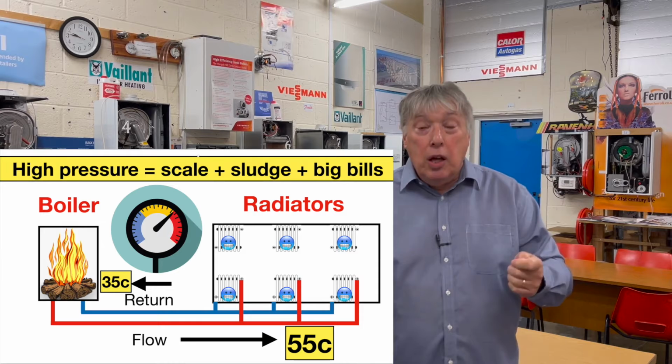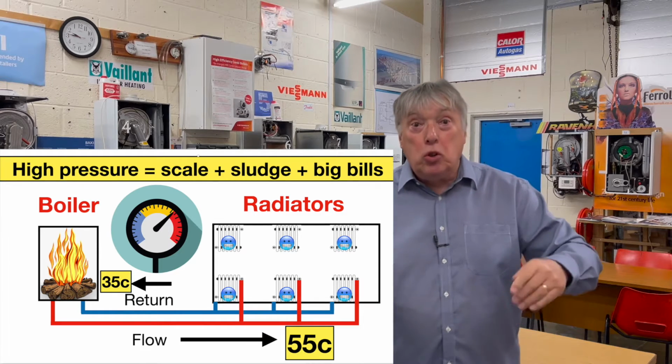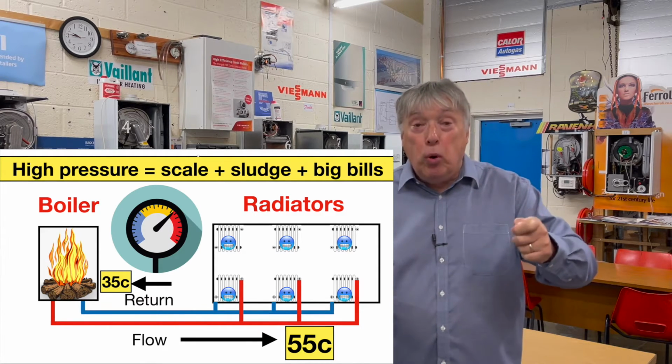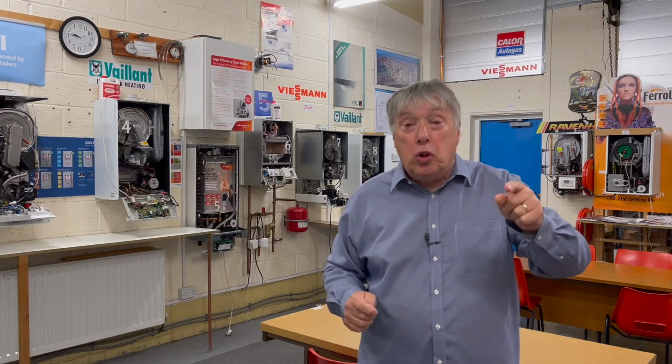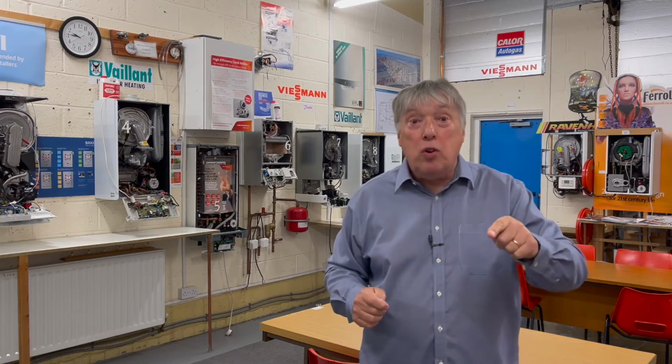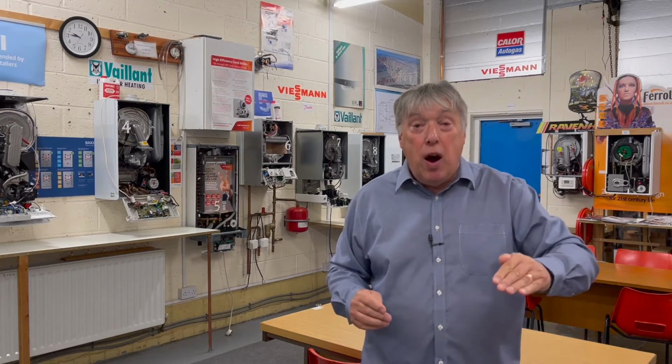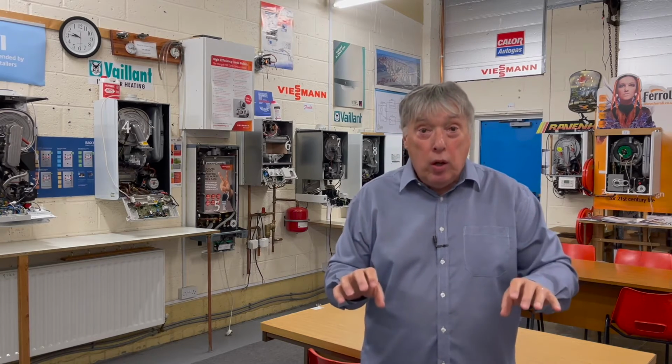of the heating is going to be a lot lower, because at the moment most boilers pump out hot water around 75 or even 80 degrees. Bringing that down to 55 is going to make a huge difference to the temperature of the radiator. It's going to be a lot cooler. So therefore, is it large enough? And that's where this app comes into play.